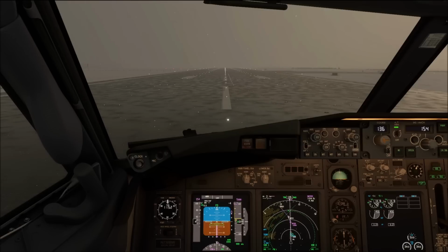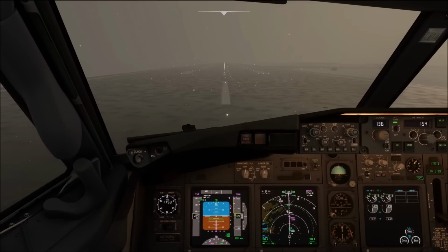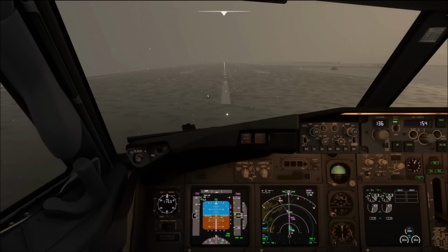So, the following procedure is going to increase situational awareness and prevent the aircraft from moving accidentally. Just to be entirely clear here, if the runway is slippery, then running the engines at 70% might make the aircraft move. If that happens, continue into a takeoff and forget about the ice shedding procedure. The engines are designed to take the stress, however, it is better for the engines to take things slow.